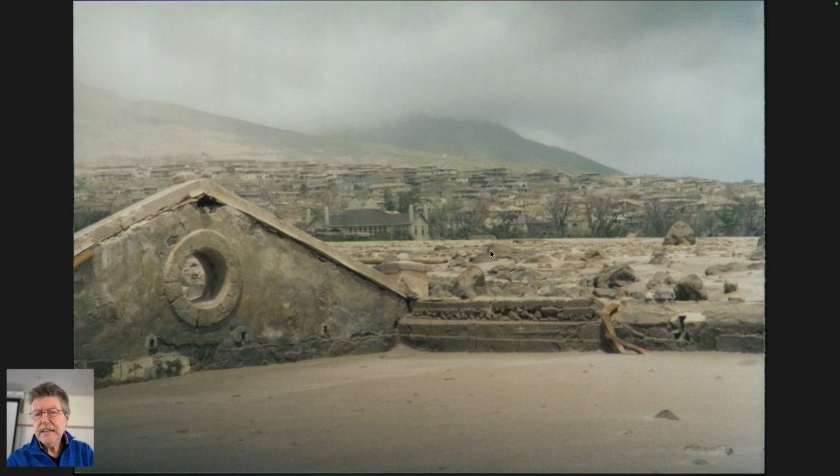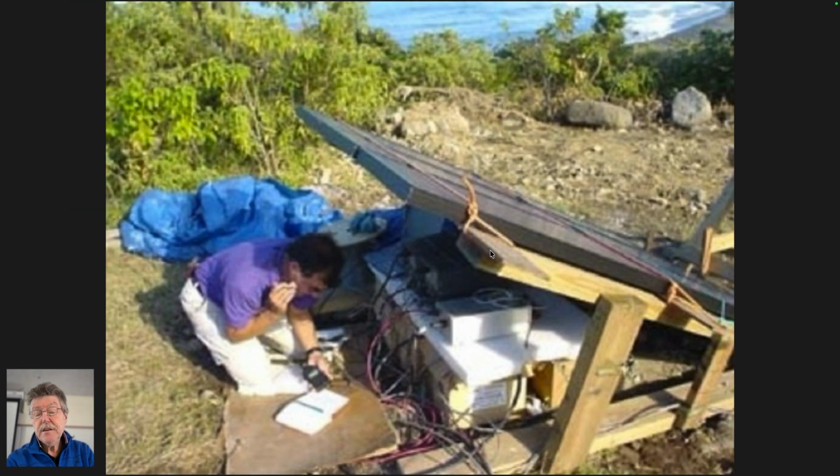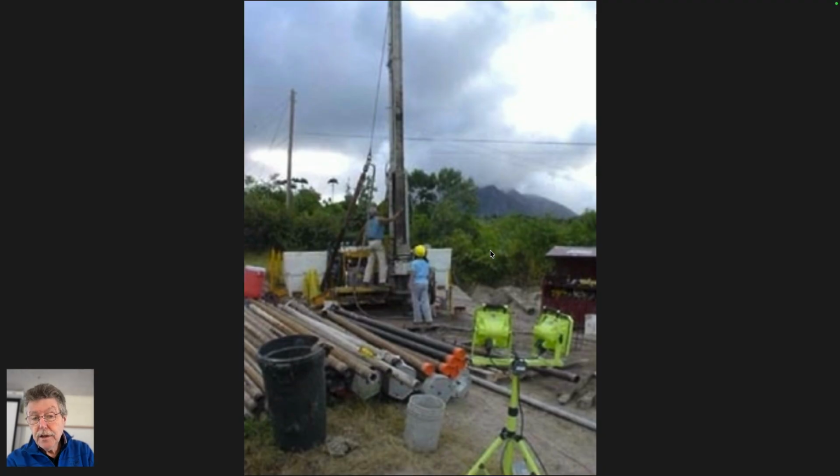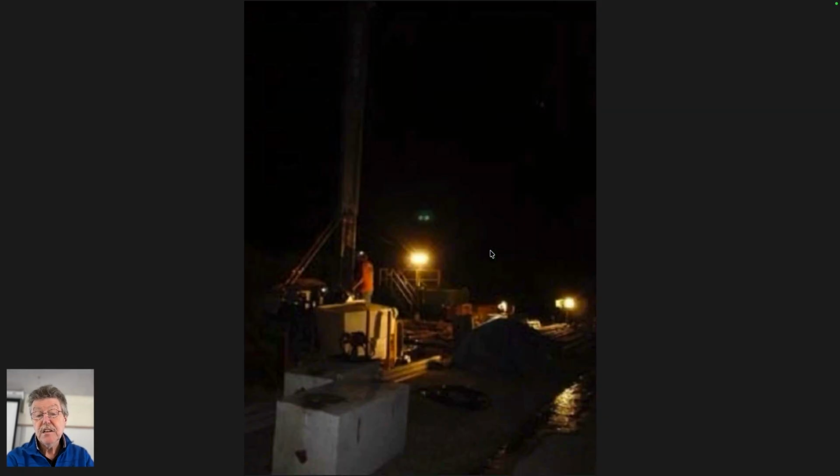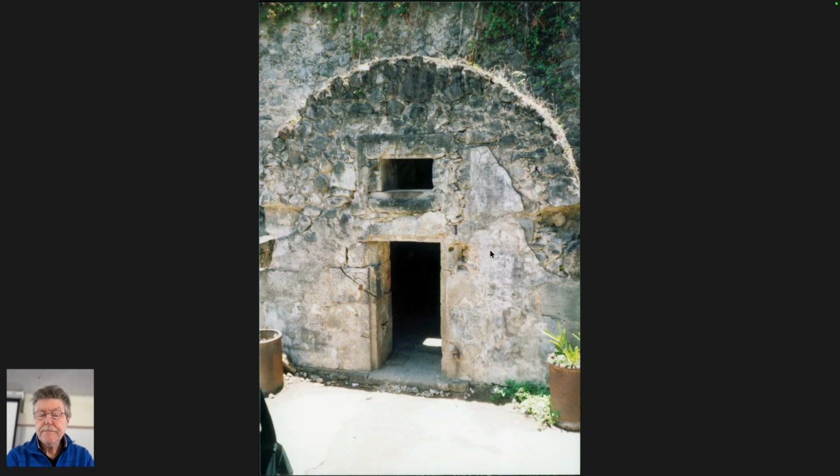So these would have been taken in the early 2000s, I guess. GPS being used to monitor what's going on. Drilling actually close to the site that I pointed out, using a particular kind of exploration rig rather than a production rig, to drill down to, in this particular case, 200 meters to put in seismometers and tilt meters that are deep enough that the noise from the surface doesn't register, because you're 200 meters deep, and the signal to noise ratio is much higher. Drilling 24 hours a day, because the rig's on site, so you might as well use it all the time.